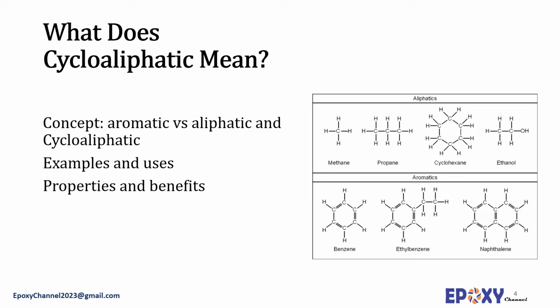They provide higher chemical resistance, thermal performance, and UV stability. Cycloaliphatic compounds show improved weatherability, water or moisture tolerance, resistance to blushing and water spotting, and better chemical resistance. When cycloaliphatic structures are employed for the synthesis of epoxies, cycloaliphatic epoxies are produced.